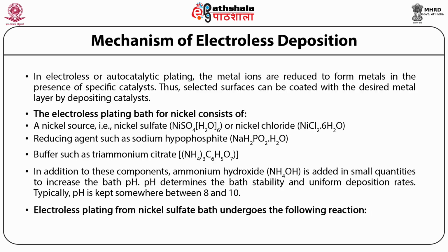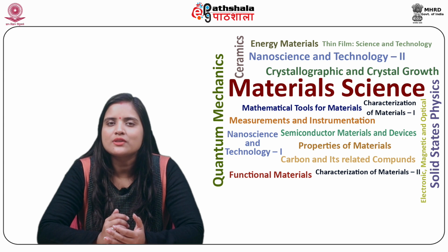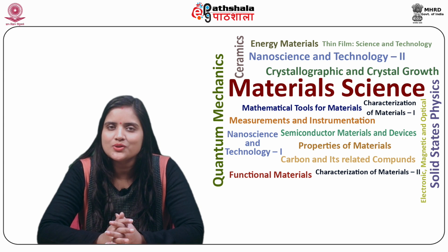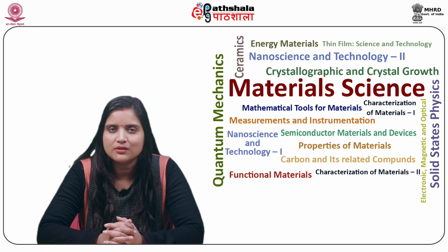Electroless plating from nickel sulfate bath undergoes the following reaction. NiSO4 plus NaH2PO2 plus water will give nickel plating plus NaHPO3 plus H2SO4. Let us now study the electroless deposition method.